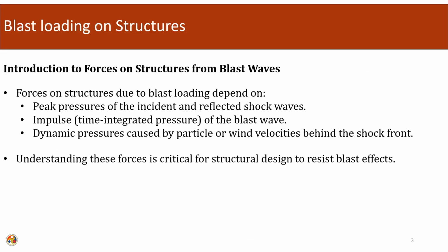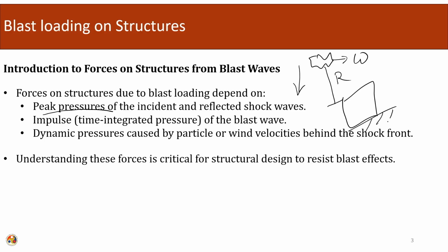So, introduction to forces on structures from blast wave. We will now see how the forces due to the blast waves are transmitted to the structure. So, forces on structure due to blast loading depend upon peak pressure. Okay. So, earlier we have seen that the effect of the blast loading will depend upon the weight of the blast, the distance between the structure and the blast, the orientation of the structure, the geometry of the structure, the configuration of the structure, the material of the structure, and after that we have seen that we are assuming that the structure is rectangular, it is seeing a planar wave front, and the structure is located above ground.